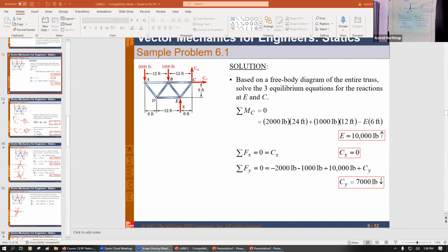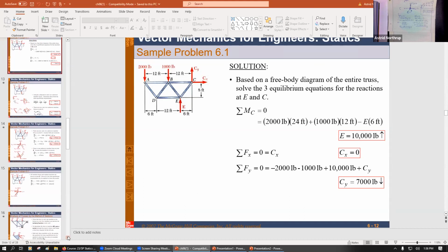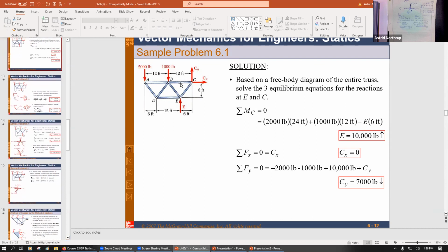Okay, so then the next thing one would do is you can chase that back. Now you know, for example, what B sub C is. And we know that the magnitude of B sub C is 5,250. We know that it's pulling on the joint. So the only weird factor is that when we get over to B, it's no longer pushing over to the left. It's still pulling on the joint. So in other words, it switches absolute direction. So in other words, at B, did I draw that? Oh, here we go.